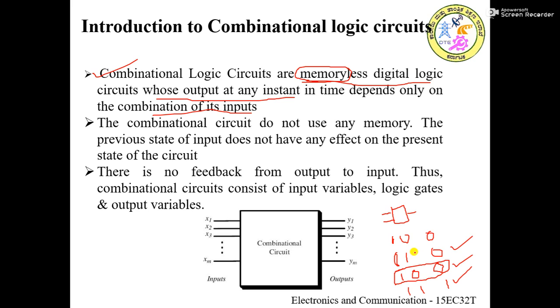So you need to remember the things. Human beings remember things in their brain. Whenever they want to predict new things, whatever data is stored in the brain will be brought into the picture. In the similar sense here also, in case of sequential logic circuits, whenever the output is to be predicted, whatever previous history information was stored in the memory will be brought into the picture. That past history as well as the present input conditions, both are going to predict the output.